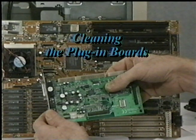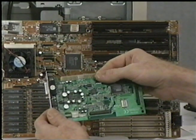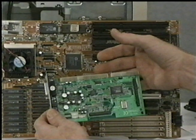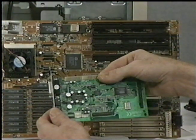Since we've cleaned the motherboard, now we are going to clean the connectors on the plug-in boards. Here's a common mistake that we want to avoid. When the boards are handled, people often touch the connectors, coating them with oils and residue from their fingers. This will prevent the contacts from making a good connection with the motherboard connectors and eventually cause these connectors to corrode. So we want to avoid touching these connectors if at all possible.